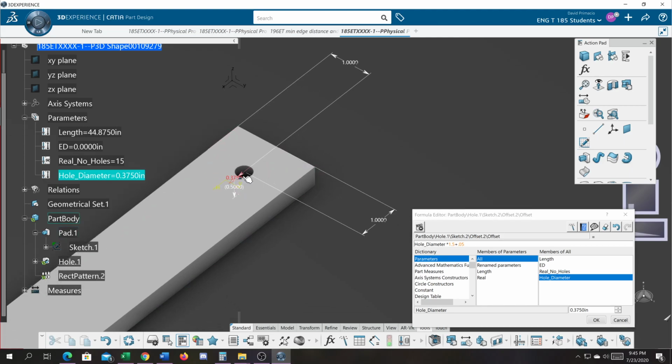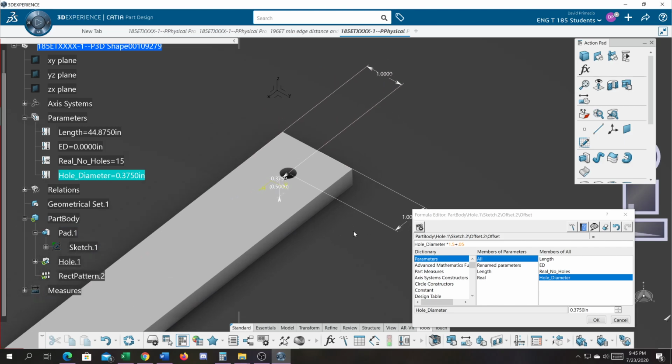We want edge distance so we don't get too close to the edge of the part. We don't want that hole to create a stress where it's going to rip and break free over here. I always compare it to hanging a poster on the wall. If you put your thumbtack too close to the corner of the paper, sooner or later it's bound to tear off on you. So you want to get it further in so you got a lot of meat holding that hole in there, or probably a bolt or fastener going through that hole that can handle that kind of stress.